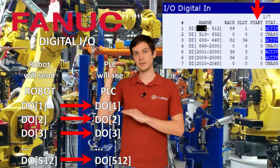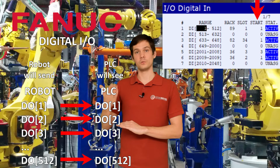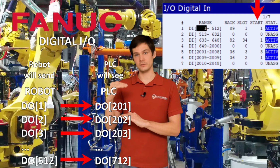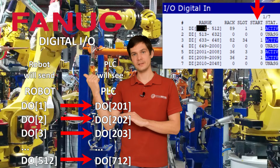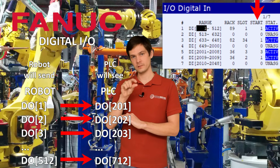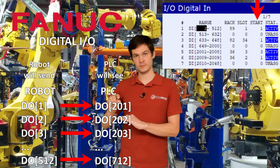So if you were using 512 bits and you put your start number as, I don't know, 200, that means the output number 1 that you will send to the PLC is going to be actually output 200.